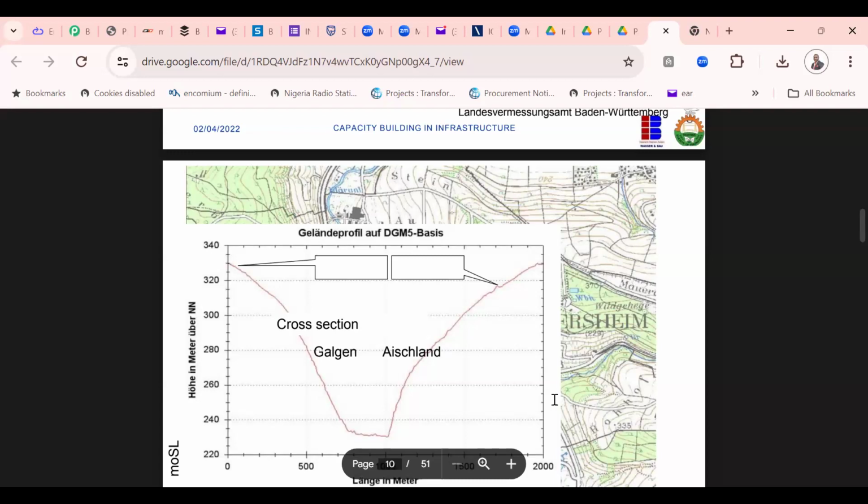Abuja has about 6 tanks. They are going to be up to 10 tanks, but 6 tanks have been built. So every region, who say zone 1, has a tank supplying it water. Maitama has a particular tank supplying it water. Apo has a tank supplying water. Gwarinpa has a tank supplying water. But there is a single pipe from the treatment plant supplying their water. So if you look at it, that system is decentralized. They are not all coming from one tank. But the treatment plant is centralized by virtue of location in Lower Usman Dam.